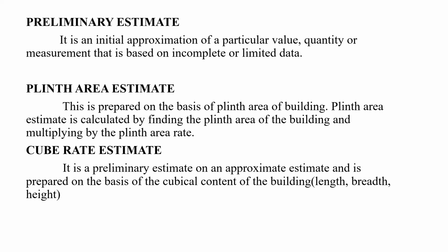Next, plinth area estimate. This is prepared on the basis of the plinth area of the building, the rate being deduced from the cost of a similar building having similar specification, heights, and construction in the locality. Plinth area estimate is calculated by finding the plinth area of the building, and it is multiplied by the plinth area rate.